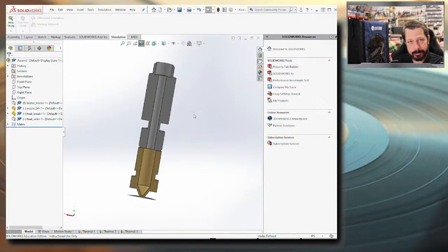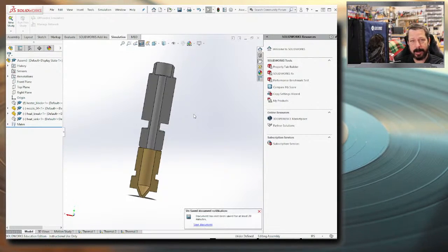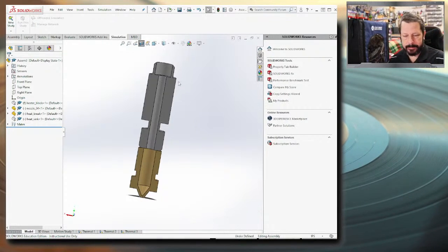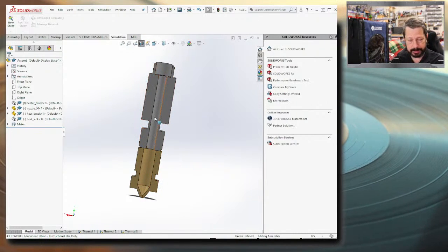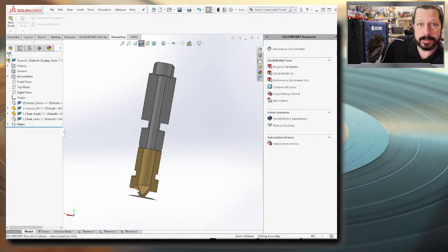probably, unless you have an upgrade or maybe a non-standard Ender 3, you would have the ability to take this nozzle off, remove the nozzle, leave the heat break in place, leave the heater block in place and everything, and the Bowden tube would be able to shove all the way through here and come out the bottom of the heat block. In fact, that's a decent way of removing clogs.